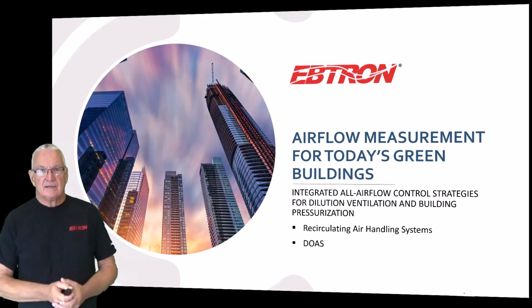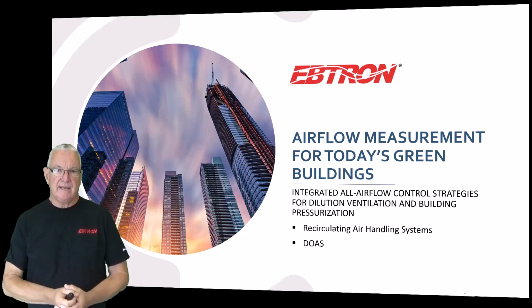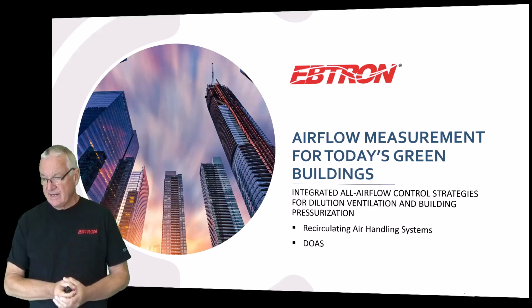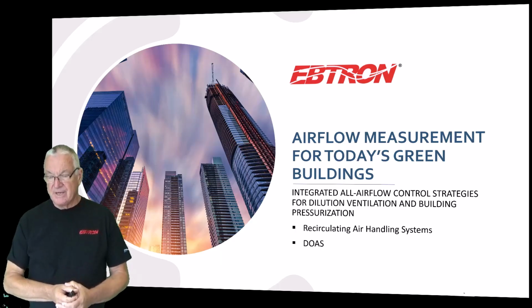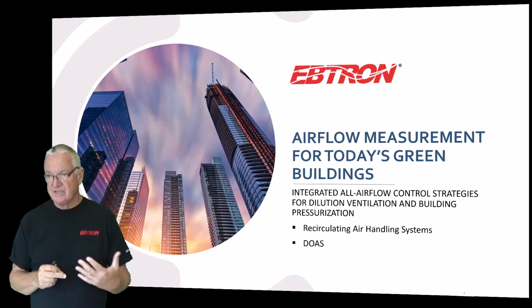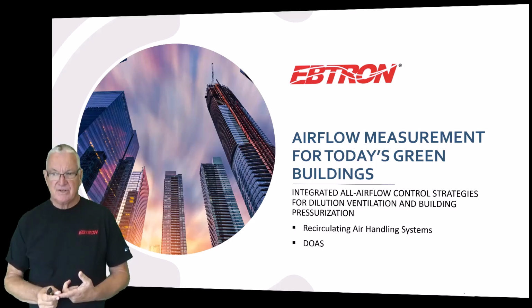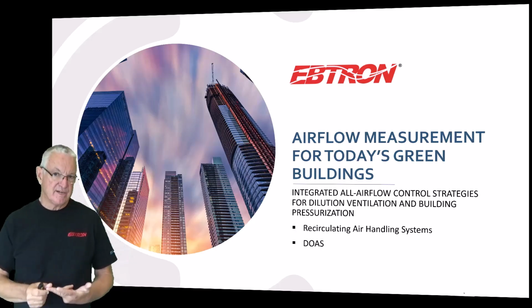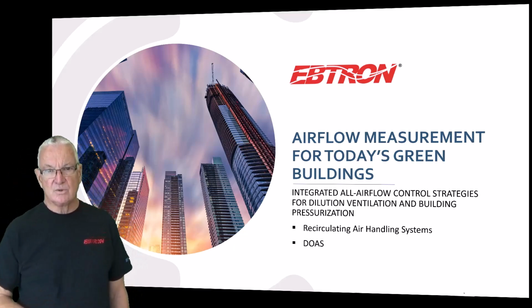Okay, now we're going to talk about controlling things, making the buildings function better. And there's a lot of different strategies we could talk about. I could certainly do outside air flow control with building pressure using static pressure, but that's not what I'm going to do. I want to do all airflow control because I have a limited amount of time, and I actually like all airflow control, meaning that we're controlling outdoor air flow rates based on measuring it, and building pressurization based on measuring the pressurization flow. We're going to look at recirculating air handling systems and dedicated outdoor air systems.